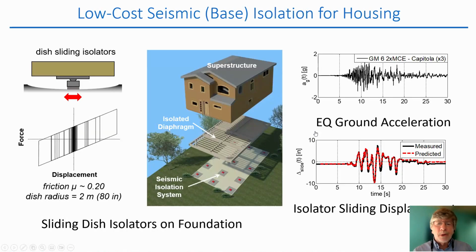So one of the projects we were involved with was to develop a technique called seismic base isolation, illustrated here in this house. This is a technology that has been used on very large structures: the San Francisco International Airport, the new SoFi Stadium, the football stadium down in LA, and other structures have used seismic isolation, but it's a relatively expensive solution. But we wanted to look at ways to come up with a lower-cost seismic isolation, using, as shown on the left, what are called sliding dish isolators.